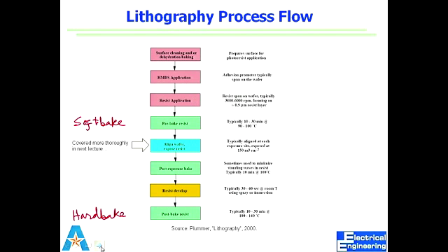But this is again what is given by the manufacturer, what will give you what kind of thickness. We do pre-bake resist, 10 to 30 minutes for 90 to 100 degrees, and we do alignment, we do exposure. Right? After exposure, we do PEB and we develop the resist. And after developing, we do post-bake resist to harden everything, harden the features. Right? So this is a typical process, typical run.